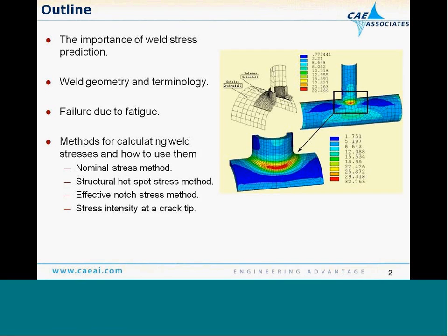We'll go over those in detail, from the nominal stress method, where we're just looking at a P over A, M c over I kind of prediction of a nominal stress, and take into account the stress concentrations in the critical local cracks and everything with an empirical deduction in the weld strength profile, down to the most extensive method where we actually physically model the cracks in the weld using fracture mechanics, where we can use a stress intensity type evaluation.